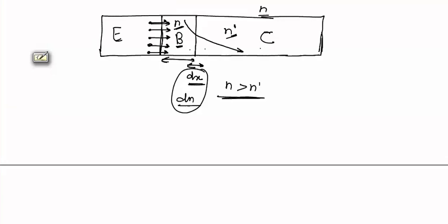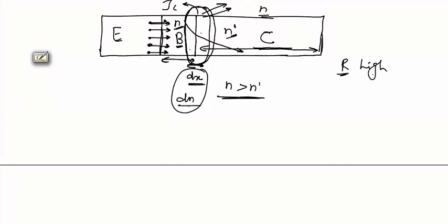Now the area of collector region is kept very large. This is kept very large to ensure that the heat generated at this collector junction should be properly dissipated to the surrounding. As this PN junction, when operated, this collector junction is always reverse biased, and for a reverse bias junction, its resistance is very high, and also the number of charge carriers that are crossing the collector junction is very large.